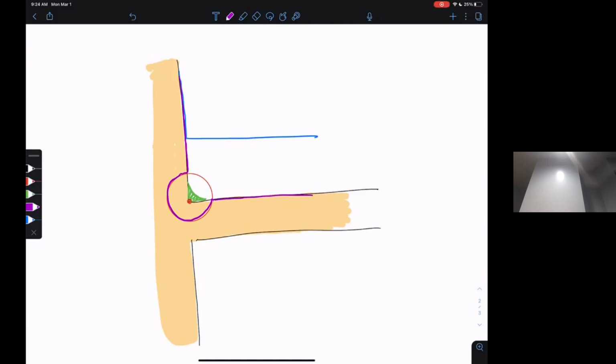And now, you only have this dotted line to fit through. That opening is not wide enough for the red bit to come in. So it'd have to cut everything, then lift up, go to that location, and then drill down like a drill. Totally doable, but there's a more efficient way to do this.